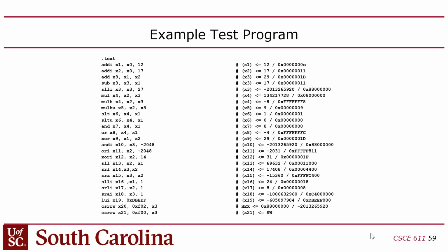The only way to know if this is working is, in the simulation environment, in ModelSim, you have to open the contents of your register file, which is something you can plot. And then make sure that as it runs, each one of these values that I have noted in the comments are written to that register. We've been trying to figure out for 20 years how to do this in a way where it can be a self-checking test bench. The reason why it can't be is that a self-checking test bench would have to be able to see something coming out of the CPU to indicate if it's working.